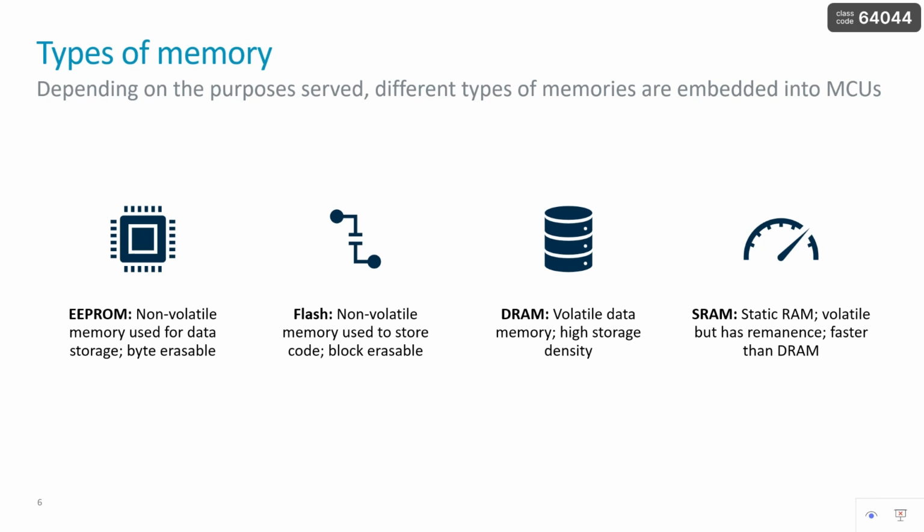You know, then we have the DRAM, and the DRAM stands for the dynamic random access memory, and it consists of capacitors and transistors. Because the electric charge of the capacitors decays over time, it has to be refreshed to avoid data loss.